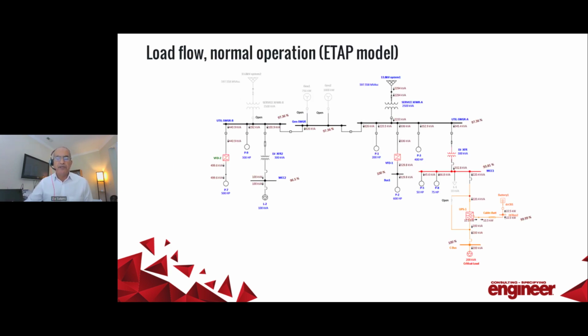Here is a typical facility which is fed from 2 feeders at 13.8 kV to the facility, and then we have a 4 kV system, and then a 480 volt low voltage system which is fed from the UPS system. The UPS is connected to AC and to the backup generator. As Nicole pointed out, the first line of source of input to the facility in general would be from the utility, and then from the backup generator, and possibly renewable, which is in parallel, and also the UPS. Therefore, the focus here would be on the UPS system.